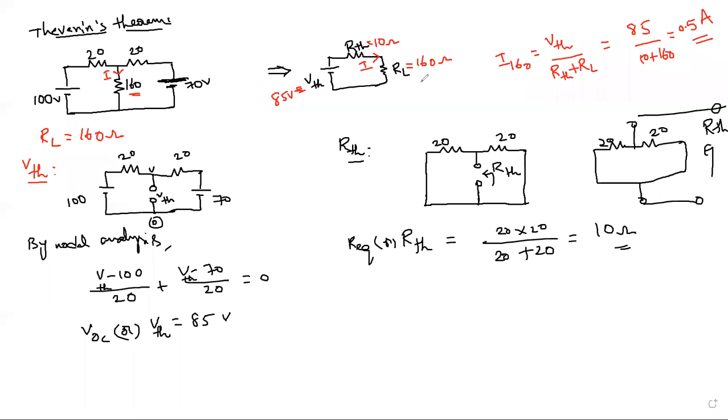They are 20 ohms and 20 ohms. How are they in parallel, sir? See, here I have written the same circuit. Just see, here there is a node. Already we calculated the node voltage in case one, that is your VTH. Right? Node means the current is going to divide, but here it is an open circuit. So I am picking these two terminals outside because these are open terminals. You can keep them anywhere, right? So if you visualize like this, then how are these two connected?